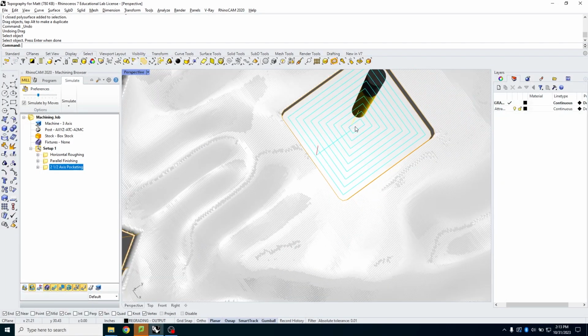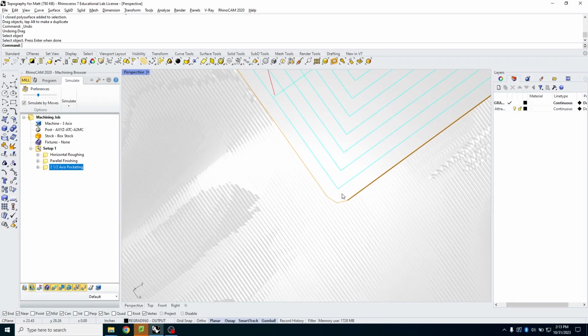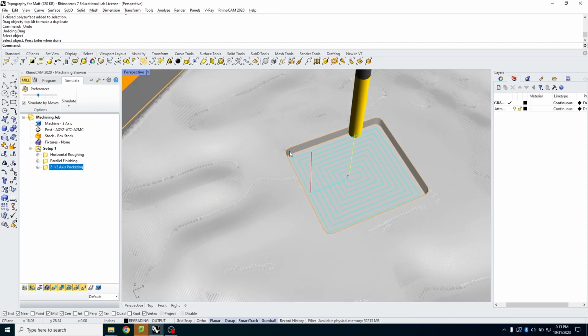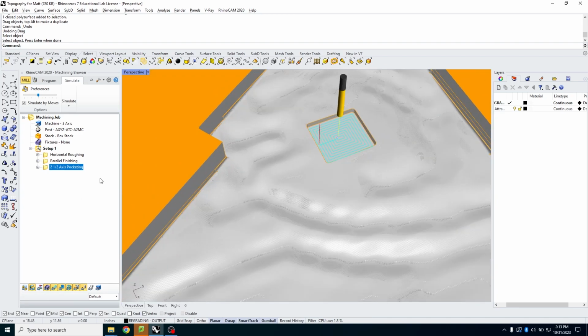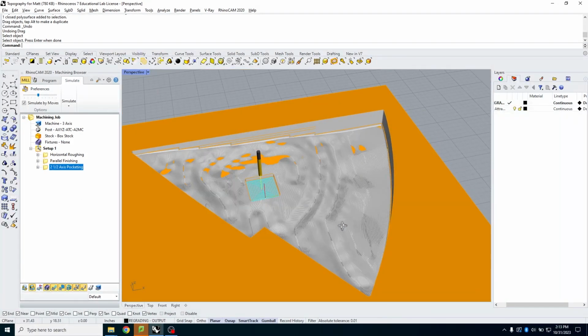It'll be pretty close. With a 1/2-inch bit, you'll have a 1/4-inch radius. So it's not huge, it's not glaring. If it's something like foam, you could probably just get in there with an X-Acto or something and cut it out so it works. But that is just so you know what you're going to end up with.